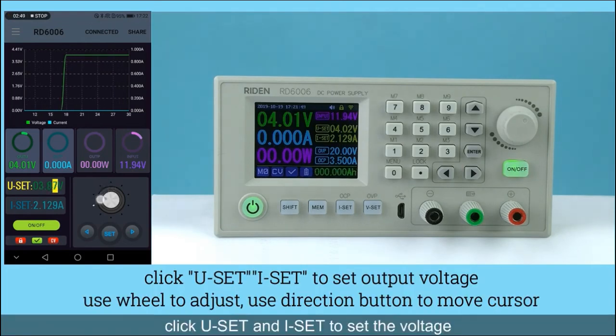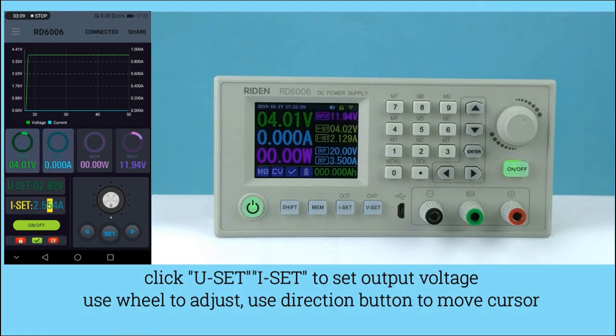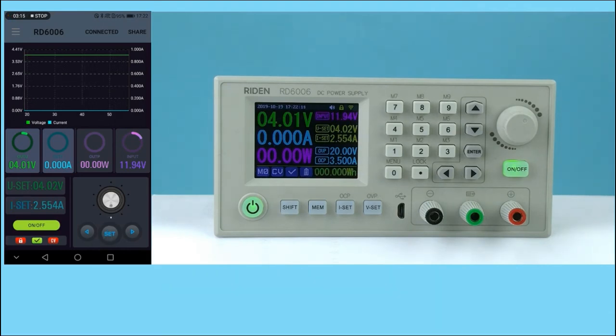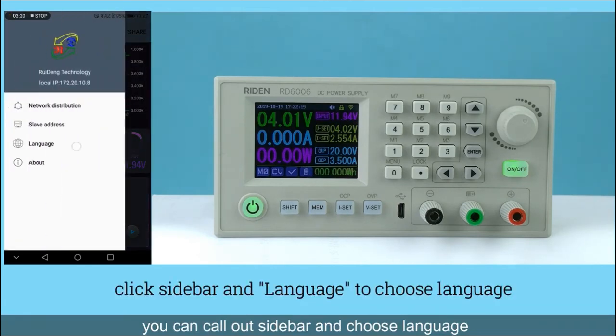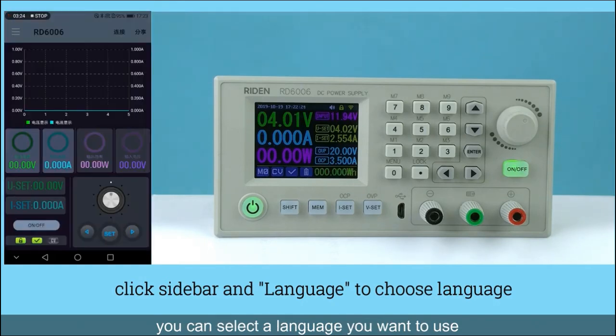Click U-Set and I-Set to set the voltage. You can use the wheel to adjust and use the direction key to move the cursor. Click Set to confirm and exit setting. You can call out sidebar to choose language. You can select the language you need to use.